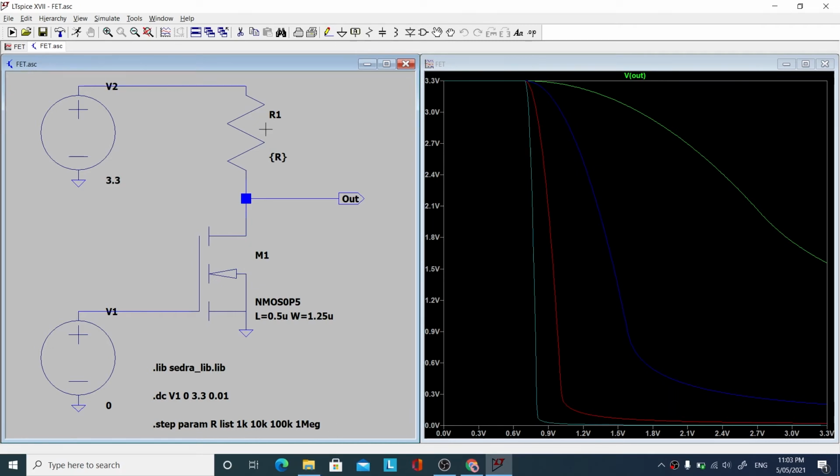There are a number of disadvantages of using a pull-up resistor that we'll cover. Here we see that the transition occurs not halfway, but closer to the low side, just under 0.9 volts, as opposed to the high of 3.3. So this does implement an inverter, but it's not desirable. We will later replace this with a P-channel FET and get exactly what we need. But for this video, we're just going to continue with a pull-up resistor here to demonstrate the basic principle.